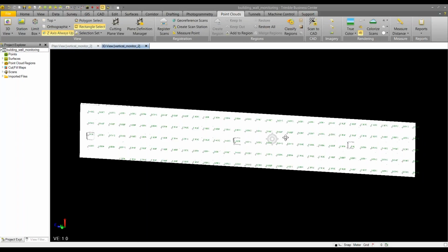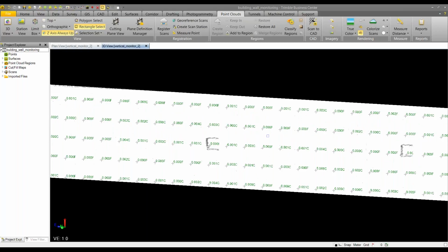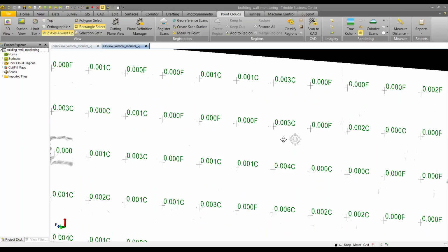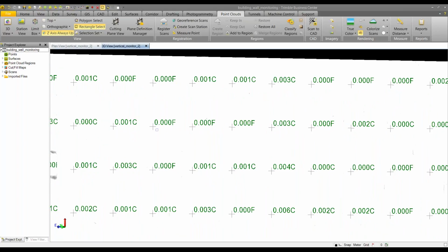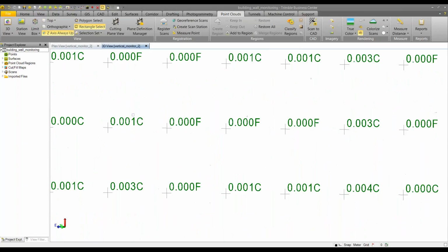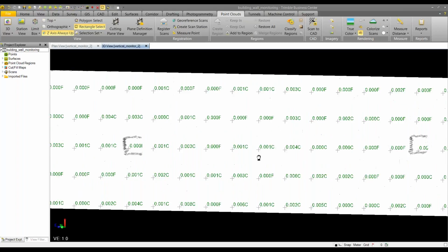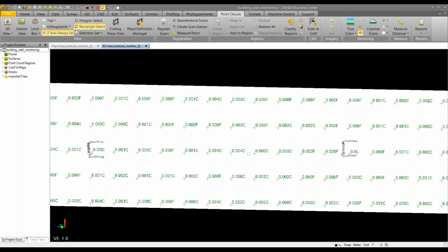This is what you would get whenever you hit OK and the cut fill map is created. Here's the grid, and there are all your cut fill marks. If you look at those units, we're talking about movement on the order of millimeters here. That's why I mentioned earlier to check your project settings and your surface settings if something seems like it's going pretty slow.